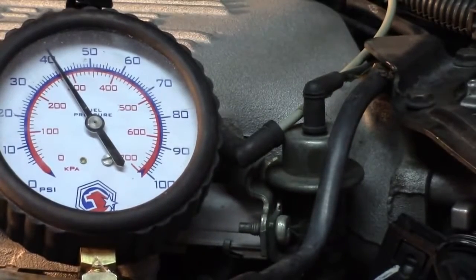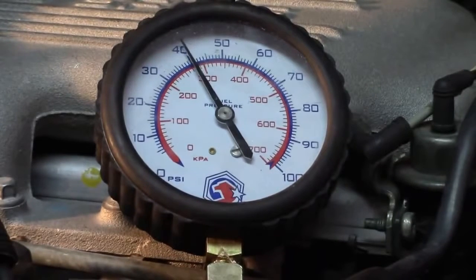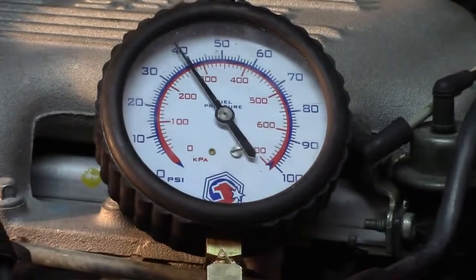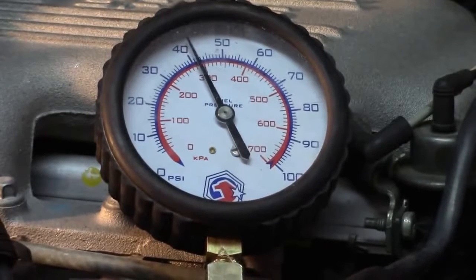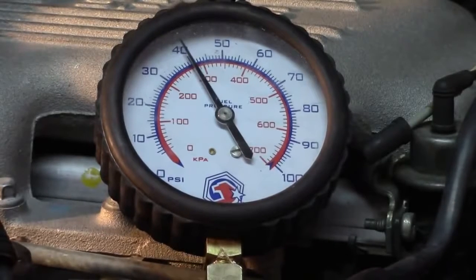Okay, so we've got the car started. We see the fuel pressure actually dropped a little bit to about 40. So one of the first things we want to do: does the fuel pressure drop when we add throttle? And we can see that it does not drop when we add throttle. If we had a P0171 or P0174 lean condition, or P0171 and P0174 on a V engine lean condition, and we saw a good drop, that would be almost certainly why we would have that check engine light code for the lean condition.